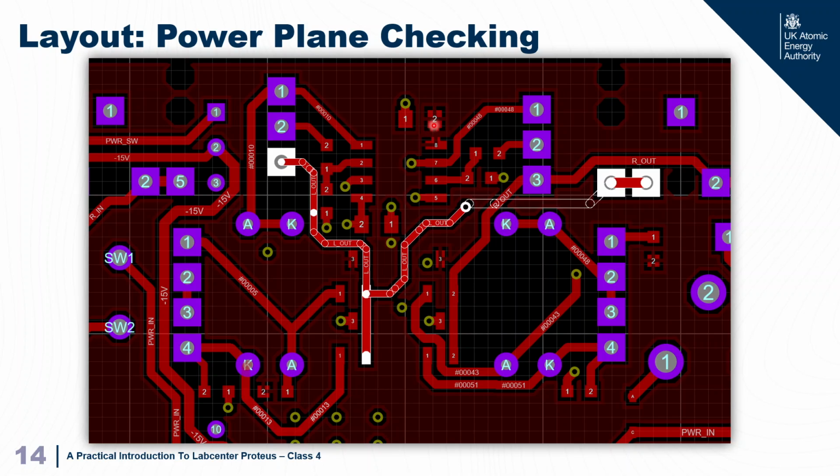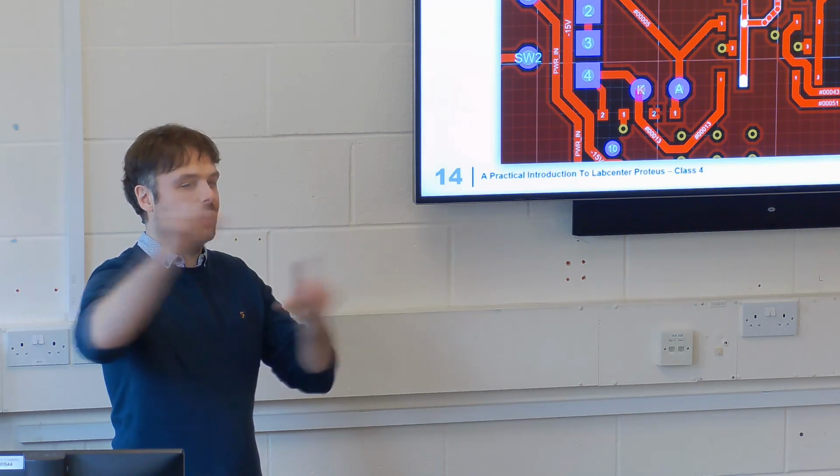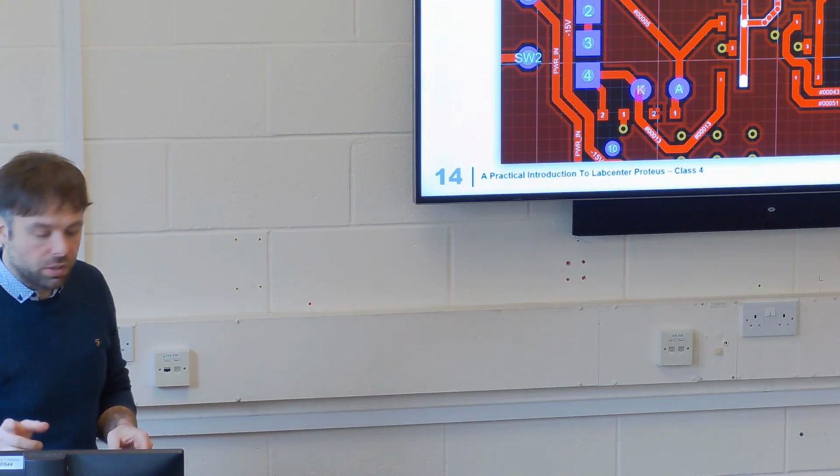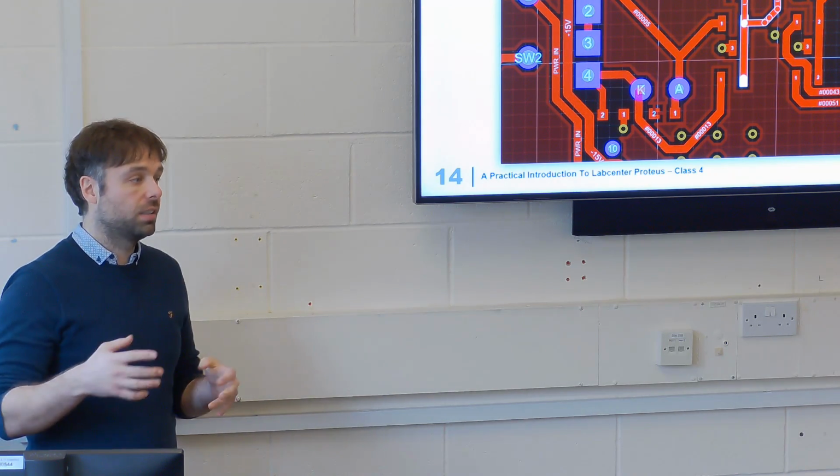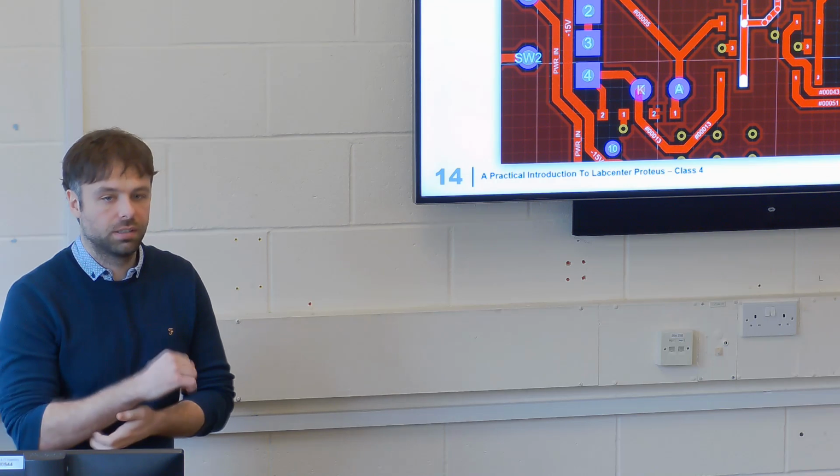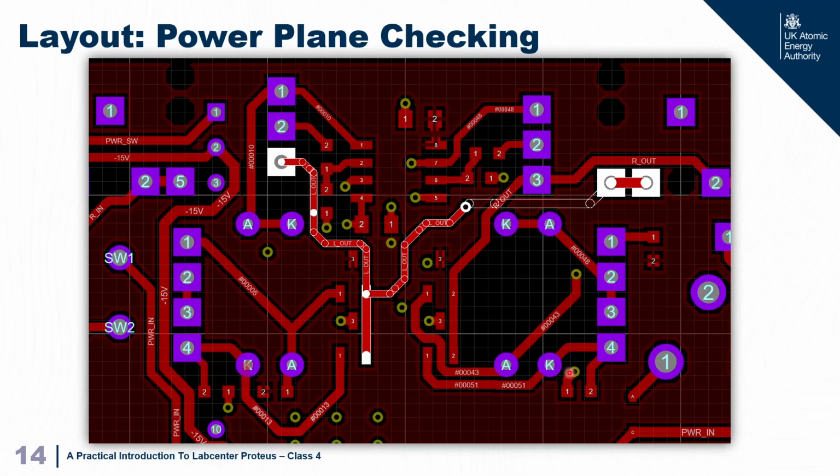Because if you think you can come through here, okay, you can get through that just about, squeezes through there, can't. So you might have created a lot of little thin traces connecting bits and pieces together on your circuit that you're not aware of. The only way to do this is to finish the design or be mindful of it as you're doing your design. You have to be mindful of it. What's the solution?